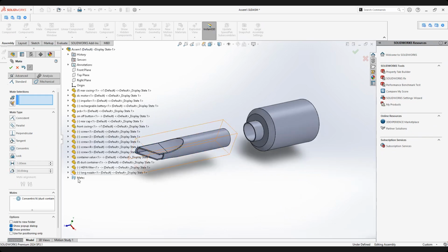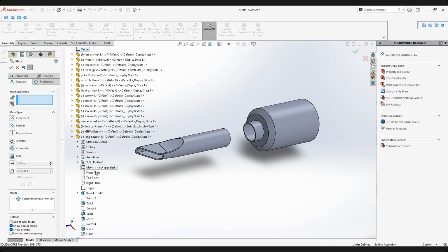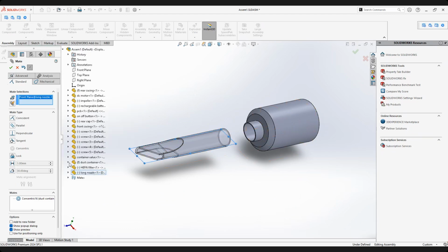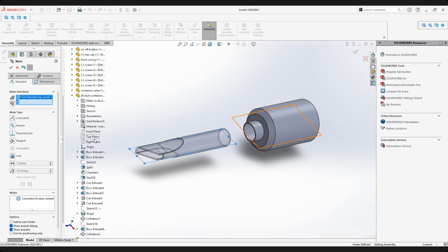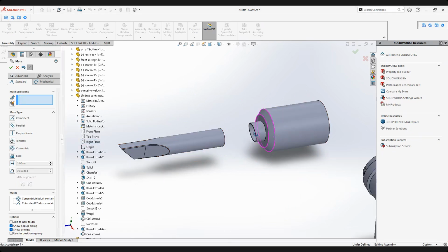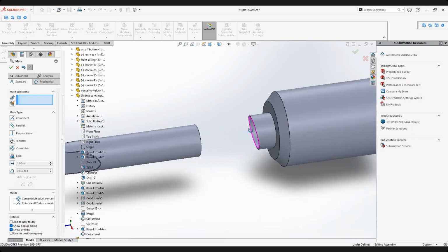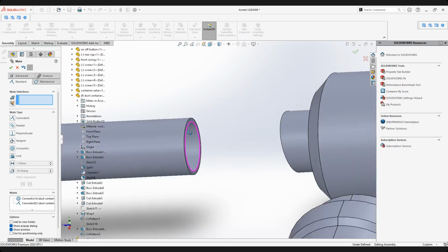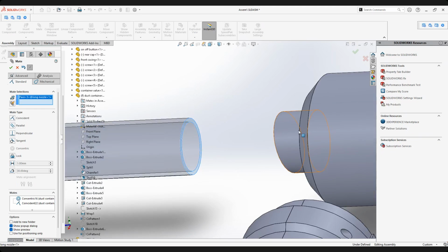So my next setting, the long nozzle front plane, no, this plane, mates with the container. So this is a container. I want to mate with the red, so it mates. Okay, but it goes to the flip direction. I go for flip like that. Okay, next setting is up until the position. This position of the nozzle will be up until this position.